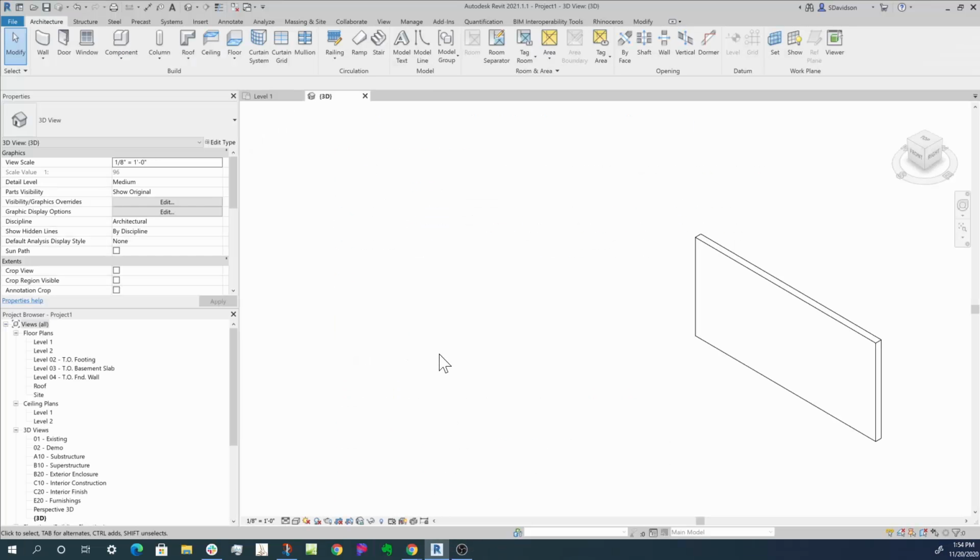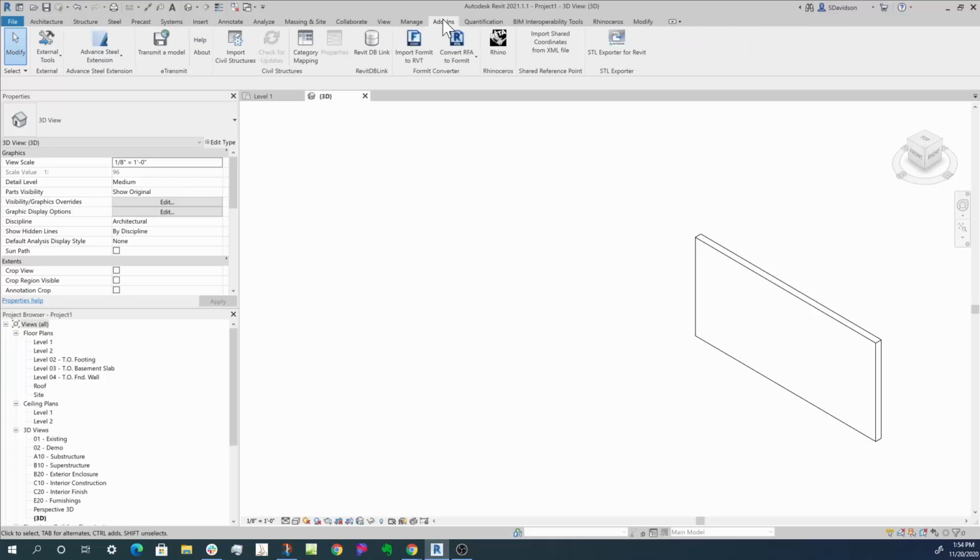And the first time you start Revit, it will ask you, would you like to load Rhino.Inside.Revit? You say yes. And what that does is on the add-ins toolbar here for Revit, you'll get a Rhino button. And in this configuration, it's not using a Rhino license or a Grasshopper license. It's just ready. And when you're ready to use Rhino and Grasshopper inside Revit, simply you press on this.